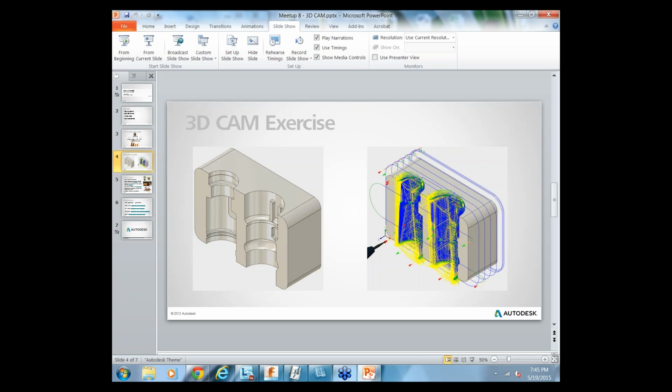You'd need to extract the projection of the face. It's 2D information basically. So if, let's say, you have a half depth pocket, you'd have to remember every pocket depth that you have, and then redo all of your CAM operations and depth operations in vCarve. vCarve is very nice for post-processing strictly 2D operations, where we're not dealing in 3D. If you did do 3D and for some reason it does not work in Fusion, you could use Cut3D. But Cut3D's 3D modeling operations are amazingly primitive compared to Fusion. So typically it'd just be better to stay in Fusion.